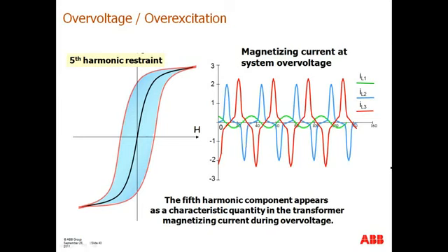And the waveform is a classical fifth harmonic, with a high content of fifth harmonic. So we could monitor for fifth harmonic content to block the differential protection during these types of conditions. And again, the issue is with that magnetizing branch, where this is not during the energization. The transformer is already energized and under load, but as the voltage on the source side of the transformer increases, the transformer starts to operate in this nonlinear region, at which point it needs more excitation current to sustain its EMF and operate.